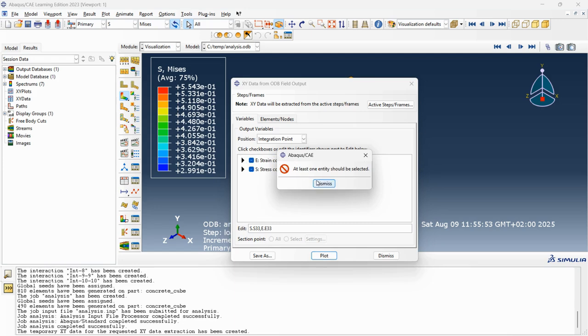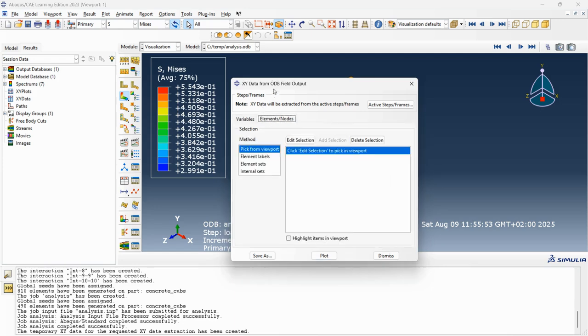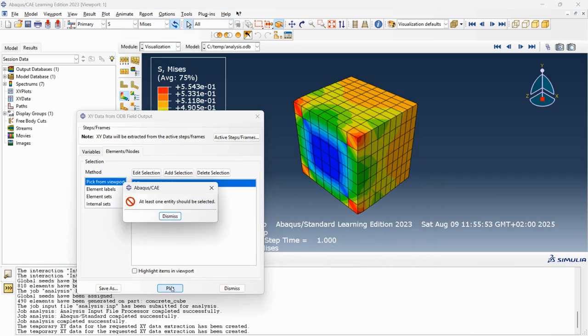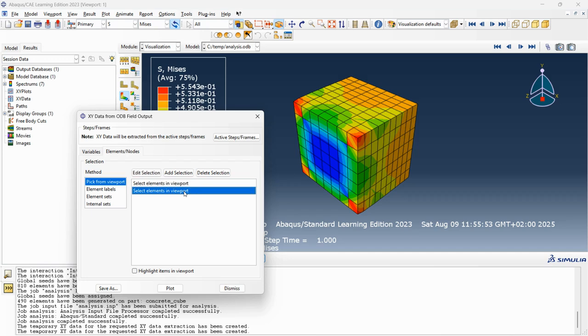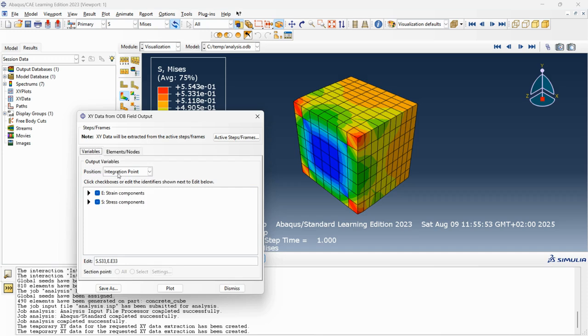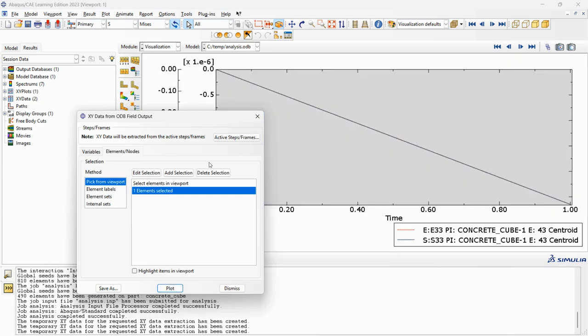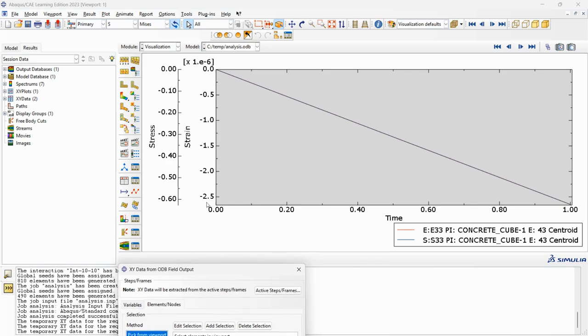And then I'm going to go on plot. No, before that I'm going to choose the element where I want to plot. I want to plot on this. Edit and then plot. It should be selected. So edit here. Yeah, I want it to be selected. Maybe I will change the variable here into centroid. And then element node, yeah, now it's selected, so I can plot it as centroid. It worked. So now I have stress and strain with respect to time, but that's not what I want.